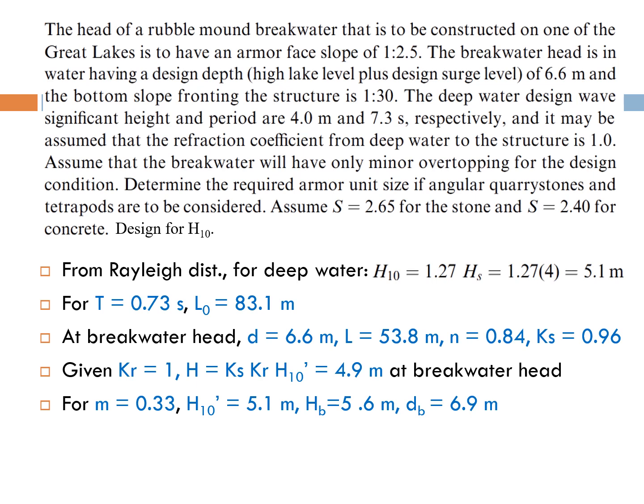Assume that the breakwater will have only minor overtopping for the design condition. Determine the required armor unit size if angular quarry stones and tetrapods are to be considered. Assume S equals 2.65 for the stone and S equals 2.4 for concrete.